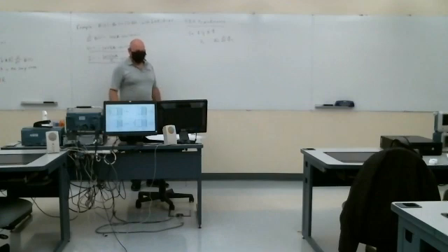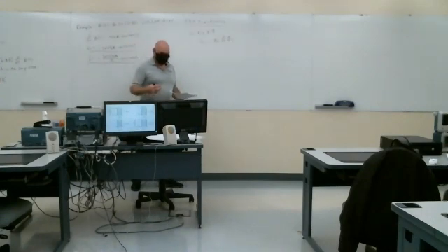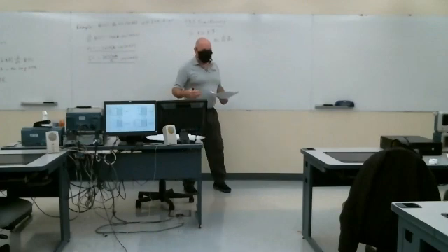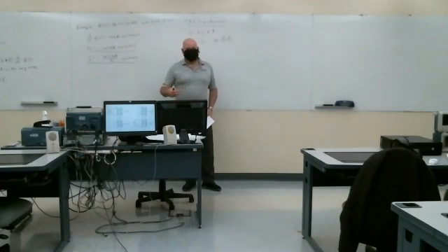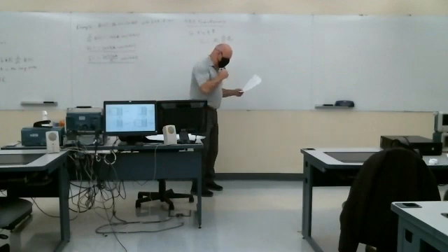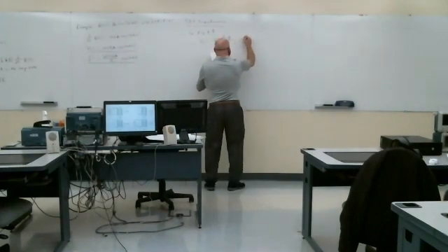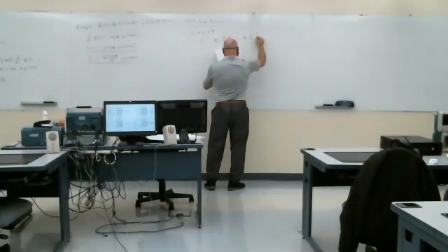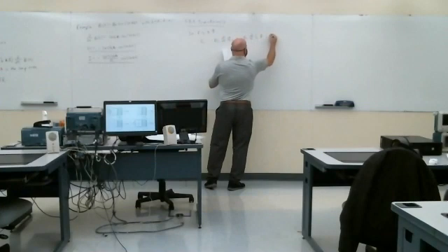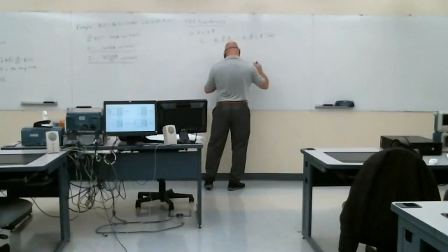So this is a simple case where we've got two coils wound on the same core, but the winding directions are really important here. So I wanted to try and project this figure so we could talk about it more. But this is minus N2 partial derivative with respect to time of the integral of B dot minus Z hat dS.